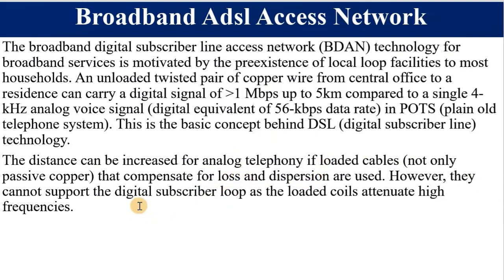However, they cannot support digital subscriber line as the loaded coils attenuate high frequency signals. You can find out from inductive reactance, XL equals 2 pi FL, meaning the higher the 2 pi FL, the higher the inductance, the more the inductive reactance.